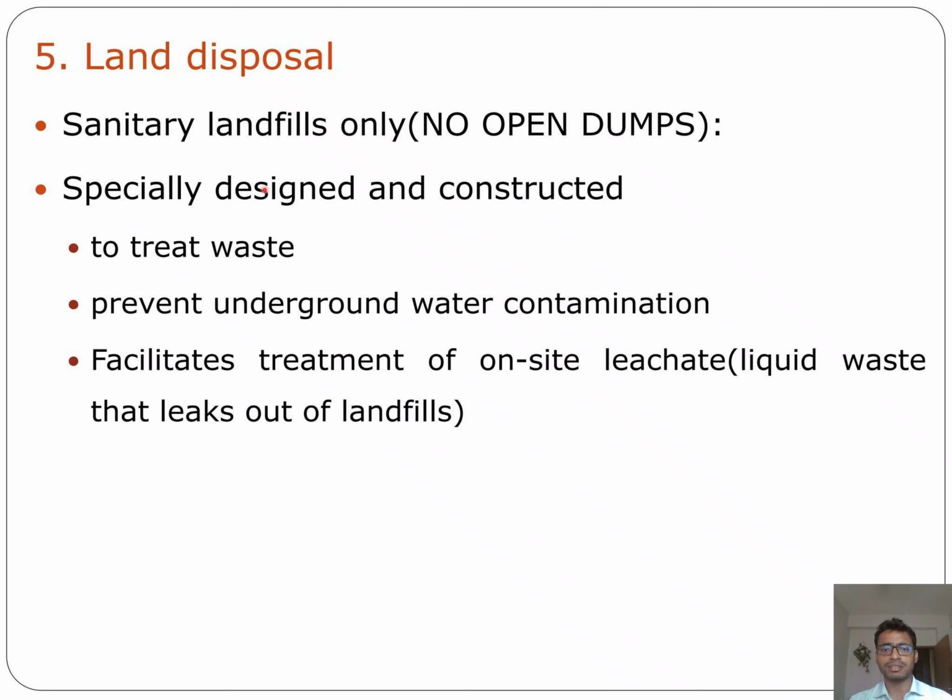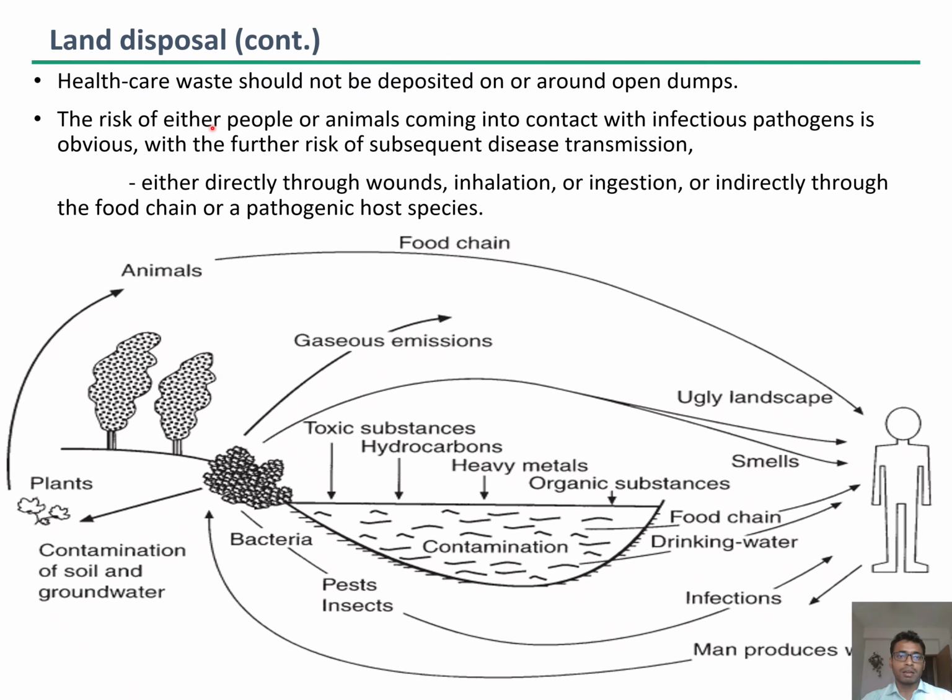Then land disposal. This is one of the most commonly used methods. We need to learn this very carefully. Sanitary landfills only, especially designed and constructed, to treat waste, prevent underground water contamination, and facilitate treatment of on-site leachates. Healthcare waste should not be deposited on or around open dumps.